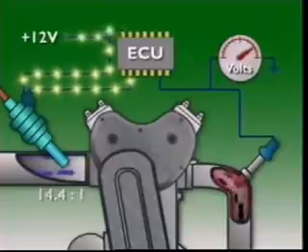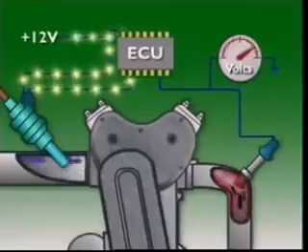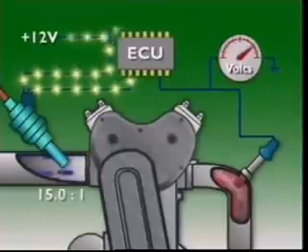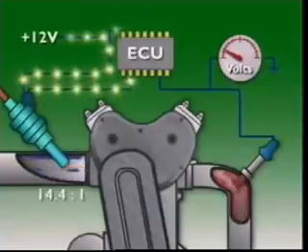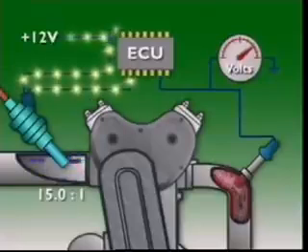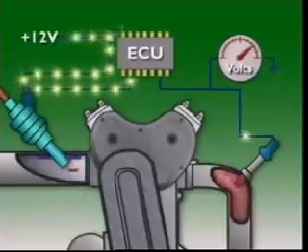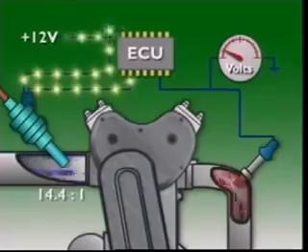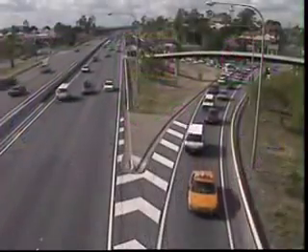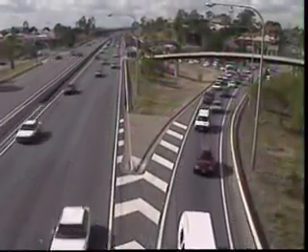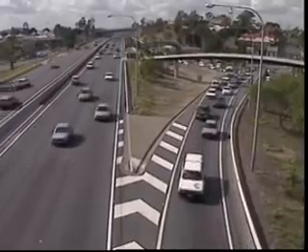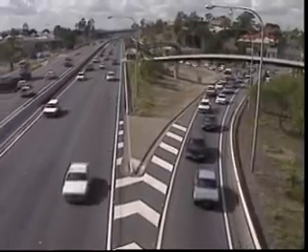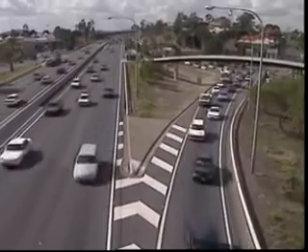If the control unit sees the voltage as high, then the quantity of fuel injected is reduced. Similarly, if the mixture changes from rich to lean, if the voltage is low, more fuel is injected to enrich the mixture. The control unit then adjusts the pulse width of the injector accordingly to ensure the most efficient operation of the catalytic converter. During engine operation, this adjusting is continuous and almost instantaneous, trying to maintain an air-fuel ratio for lambda equal to 1.